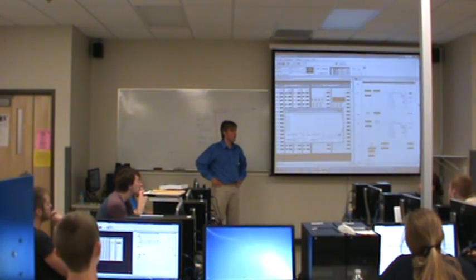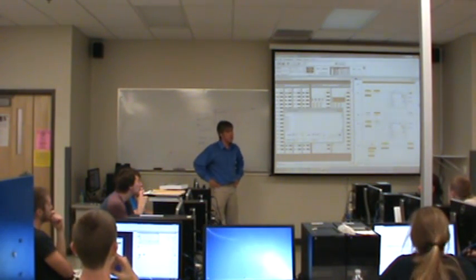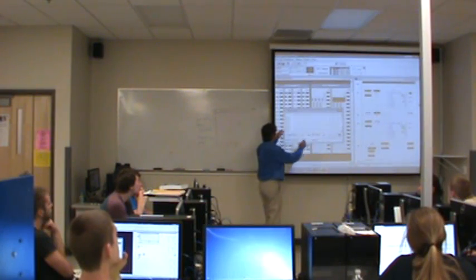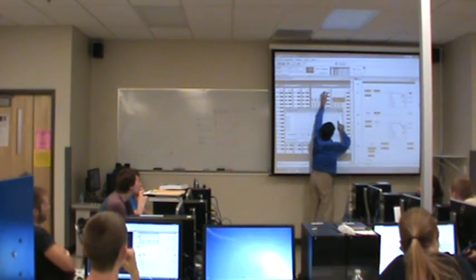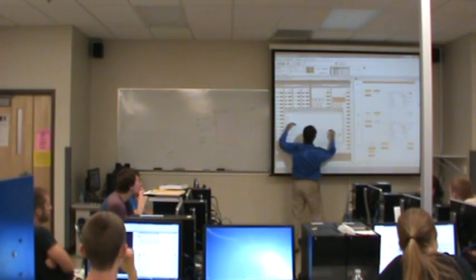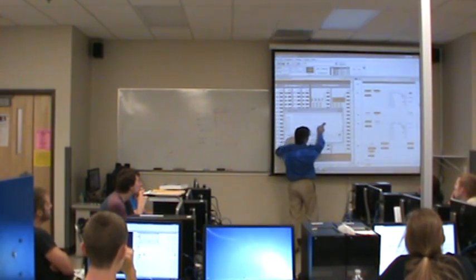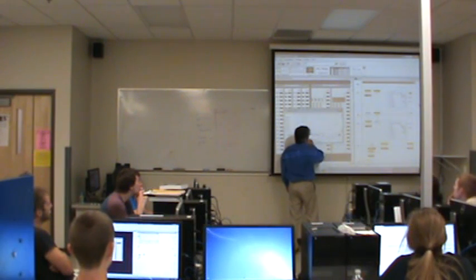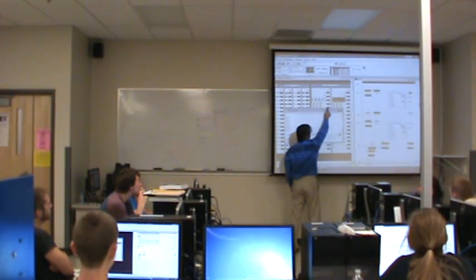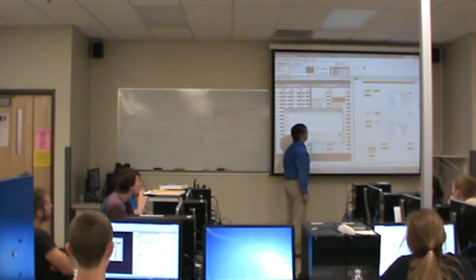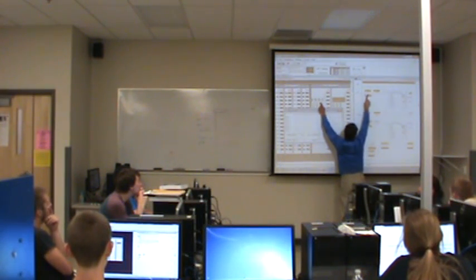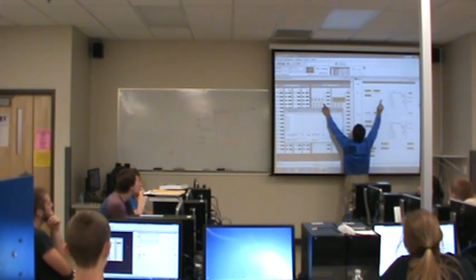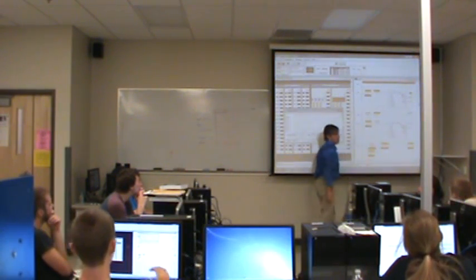Any questions so far? Well, let me demonstrate it a little bit more. Maybe you'll catch on. What it's looking for is this bit pattern. It sees that this 1 is on, so it said, I found it, it jumped to the next line, and now it's waiting for this bit to come on. It's waiting for bit 4 to come on. The way I can turn bit 4 on is by incrementing the next one. Okay, I put a note in here so I'll remember what to do. Plug in 0000, 0001, 0011, 0111, and so on.